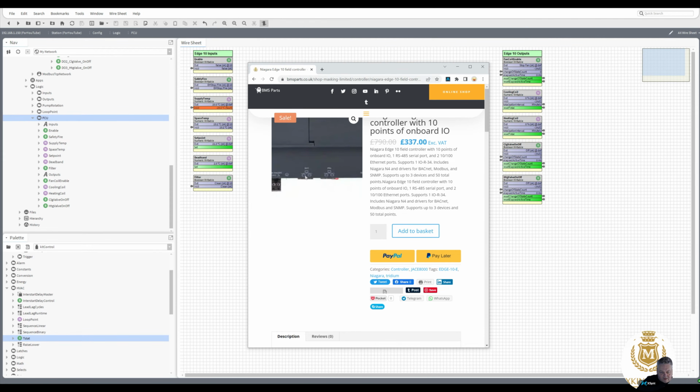Now they can actually be on the same IP range, so you can go in with the Ethernet cable from your controller, and you can link out of that to the second fan coil unit and then link again to the third, so you can daisy chain your fan coil units. We've got the debug and we've got the factory reset. Nice little controller, and that's what we're going to be using.